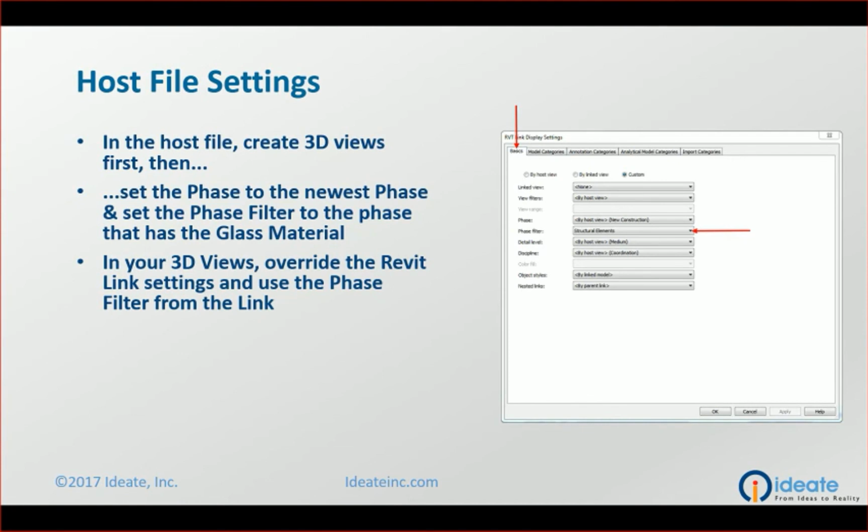And then this part. You know when you link in Revit models, you just don't want to link them in and just walk away from them. You have a lot of background work to do. Would you agree? Typically, you're not just linking in and saying everything's great. You're going to have to go and edit the settings for the structural link. Would you agree? Or whatever link you're doing.